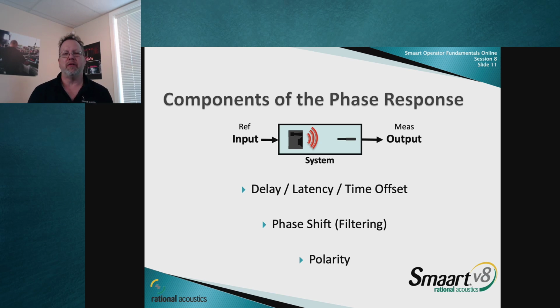And then the last piece of information that we're looking for is polarity. Now here's the thing. Polarity is going to show up differently than phase shift. So we're going to dig into that. Polarity mostly we're going to be talking about in the next episode. But let's say I have a main system and a fill system. So when I bring in that fill system, let's say it's not even the same manufacturer, and it's a box you found in the back room, so you're plugging it in to be a fill to cover some area. You need to choose the polarity that you're driving that to make it work with the other system.